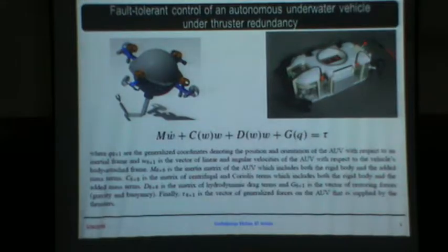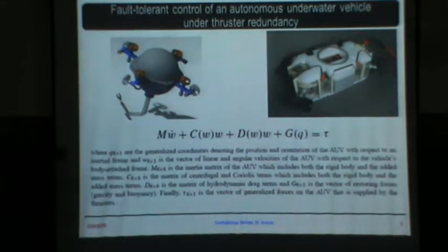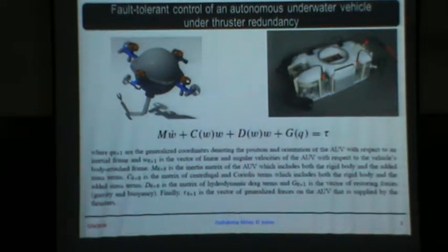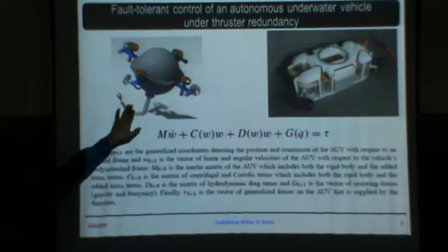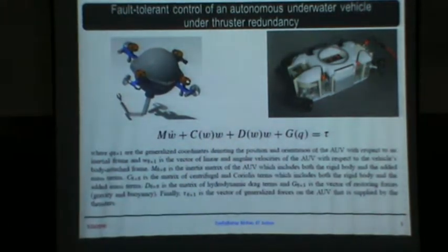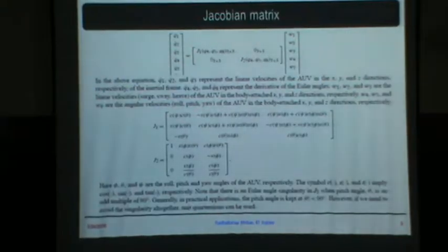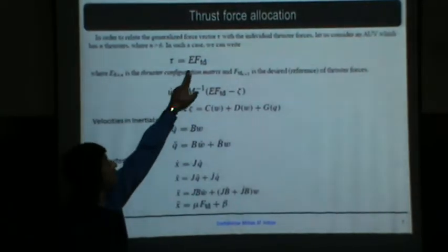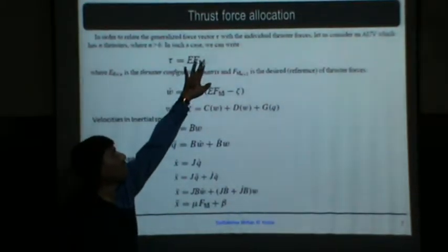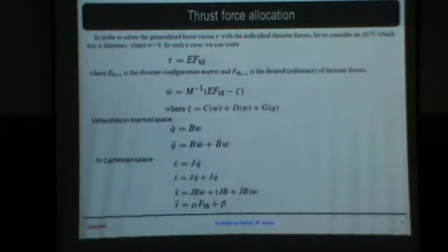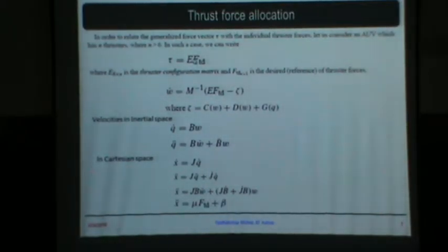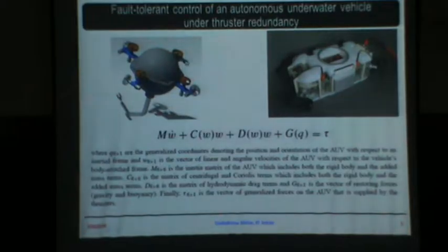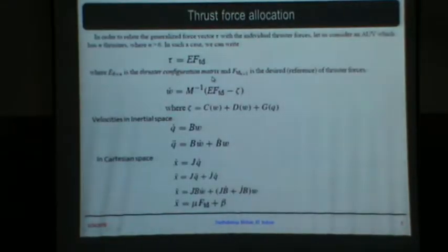So for example, this is a system with 4 thrusters and 3 manipulator motors. Totally 8 thrusters, 4 in horizontal, 4 in vertical, and 3 motors. Similarly here, 4 rotatable, so 8 control inputs. In these kinds of cases, I can apply the Jacobian matrix and get the control input like this. Now this E is my control input matrix and this is your input. The thruster TD is nothing but the thruster drive and this E is my thruster configuration matrix. In this case, the thruster will be higher.